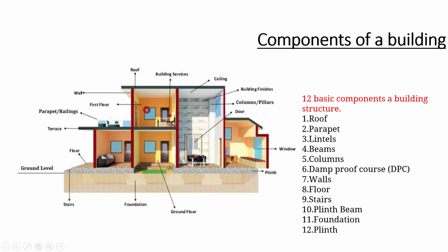That means this point will be very highly stressed, as there is a discontinuity because we are making a hole here. So in order to rectify that, we are providing a lintel, that means a beam throughout the length.